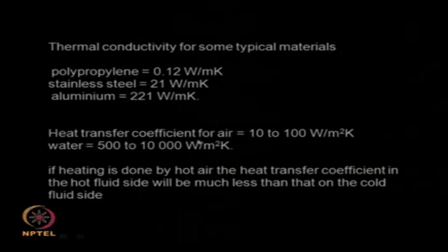Now let us look at the heat transfer coefficient for air. It is about 10 to 100 watt per meter square per Kelvin, whereas if you go to water, look at it, it is a big jump. So water has a higher heat transfer coefficient than air. So most of the liquids have much higher heat transfer coefficient than air. Air is a very poor heating medium, but then that is how it is.